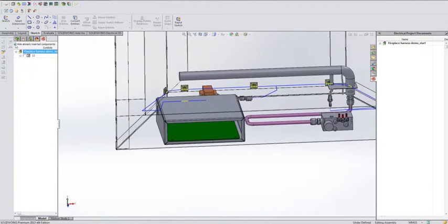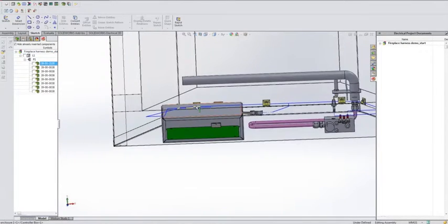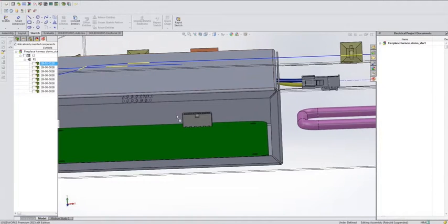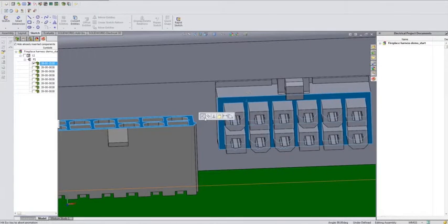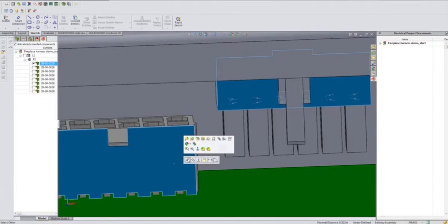If I go ahead and click on Hide Already Inserted Components and expand this out, you'll see on the mechanical side, it'll just tell me, hey, this is what I have left. If there's multiple on here and there's components already inserted, I can associate them. Or if they're not inserted at all, what I can do is go ahead and add them in. So I'll go ahead and just add in my back shell. Just add in one of those. And using the SOLIDWORKS mating techniques, I can add in some coincident mates here. This face and this one.